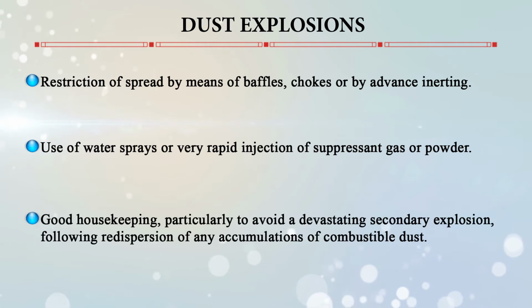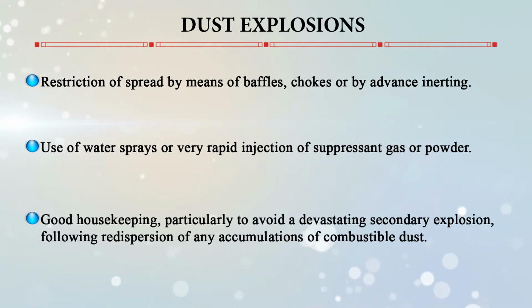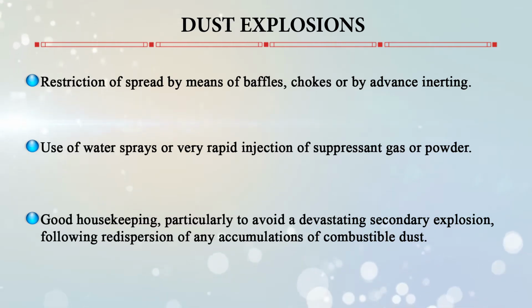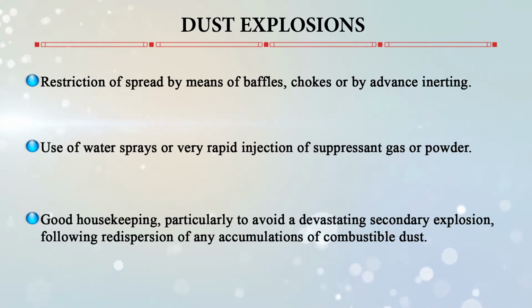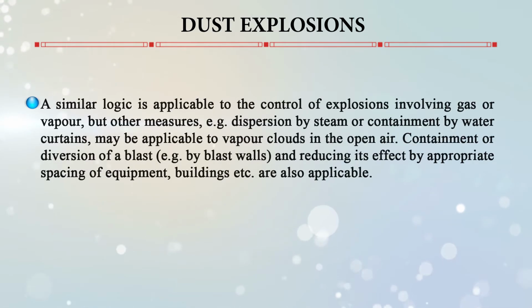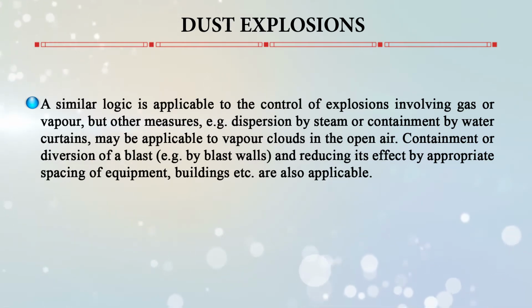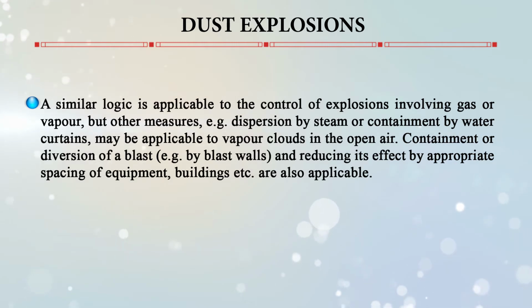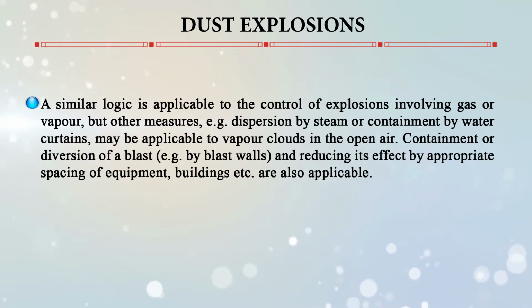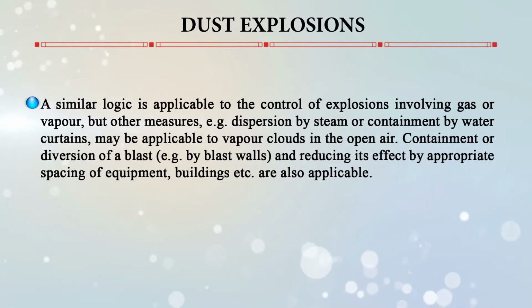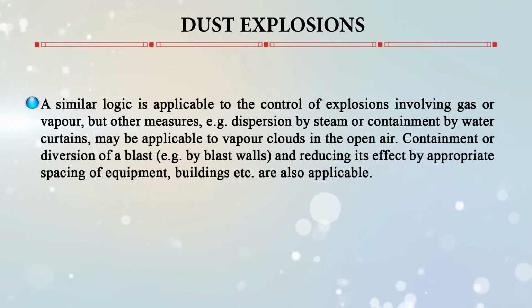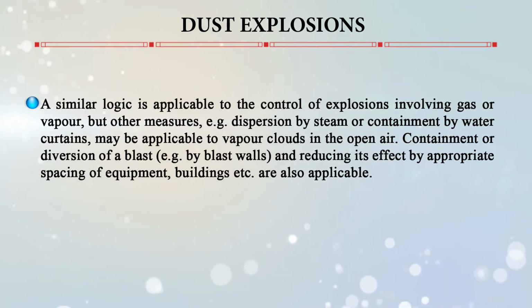Good housekeeping is also very much required, particularly to avoid a devastating secondary explosion following the redispersion of any accumulation of combustible dust. A similar logic is applicable to the control of explosions involving gas or vapor, but other measures are also there, like dispersion by steam or containment by water curtains.